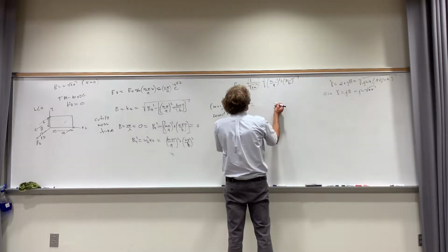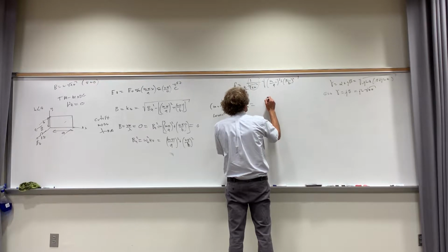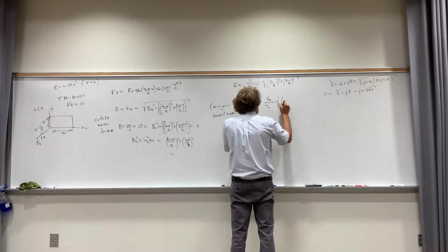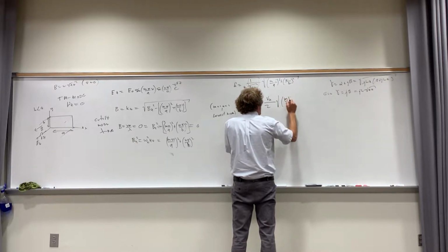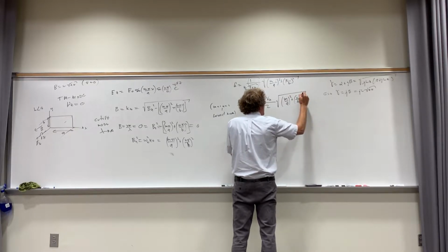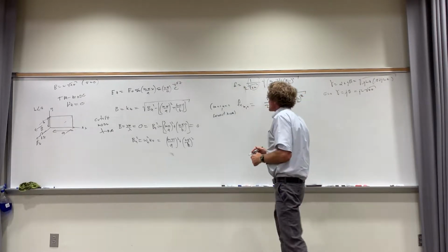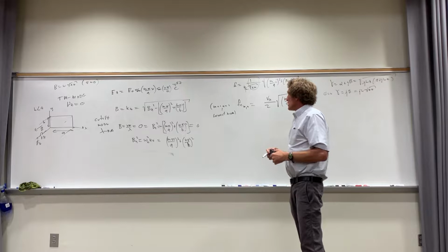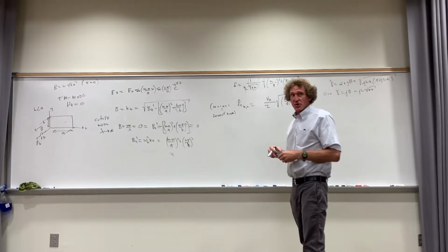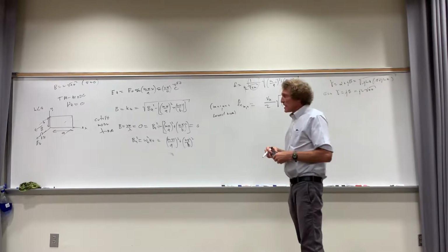So I'll call this V unguided, the velocity of the wave in an unguided media, over 2, and then times the square root of m over a squared plus n over b squared. So that, sort of redoing it, is the cutoff frequency, and you'll see this is the same thing for TE mode too, but I'm just showing you how it's developed, all right?